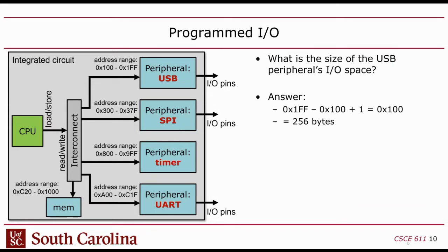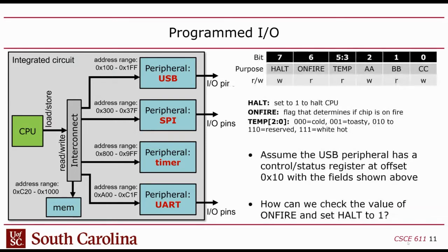As I mentioned, this is a key point in bare metal programming, because this is something that you cannot do with an operating system. An operating system would prevent you from doing direct I/O with peripherals, because the operating system would want to do that with its drivers, and the user code would just have to go through the drivers and would be operating at a much higher level of abstraction, which is the kind of code that you've written so far in our department.